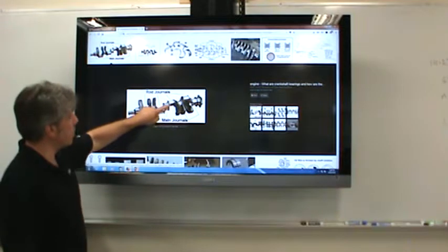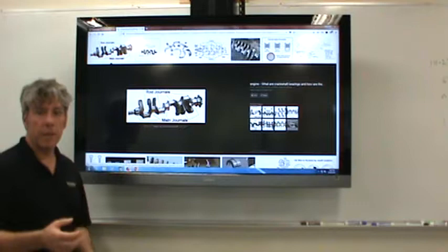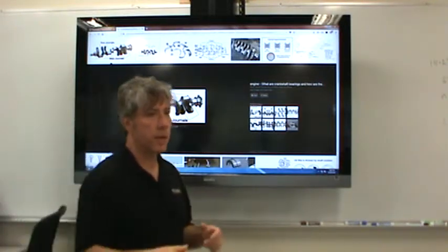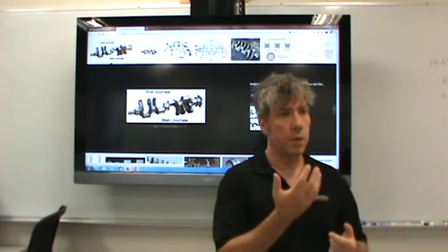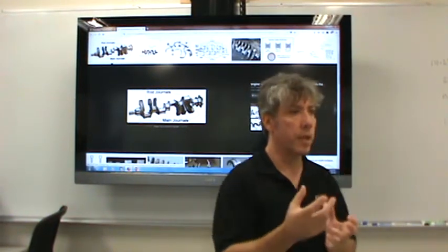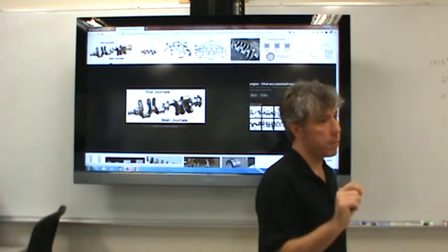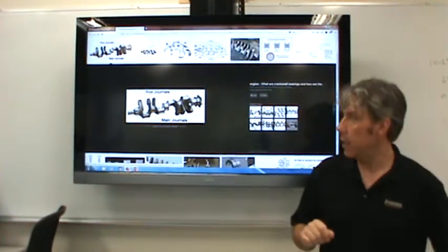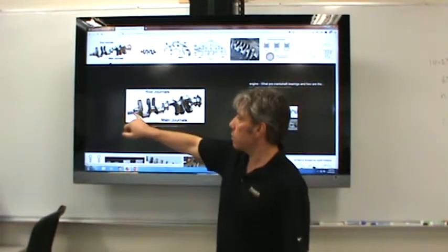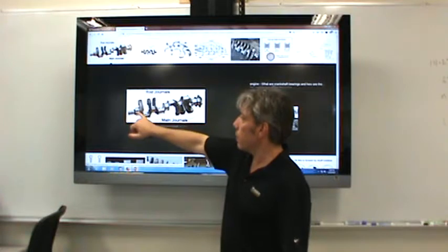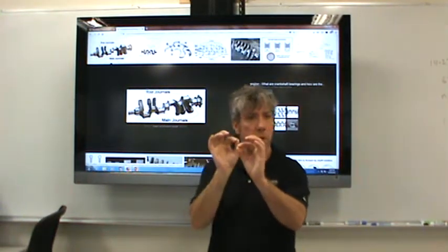All these surfaces here, you notice how they look, you can just tell they're very polished, right? Okay. In fact, when you pick up a crankshaft or a camshaft, which also has journals on it, and you look at it, those are almost a mirror finish. You can almost see your face in it. You know, it's distorted like a fun house because of the shape of the mirror, but it's still a very fine surface finish. And the reason for that is that the tolerances are very low. The tolerances between, if you think about all these journals, they have to be down almost a perfect line, right?